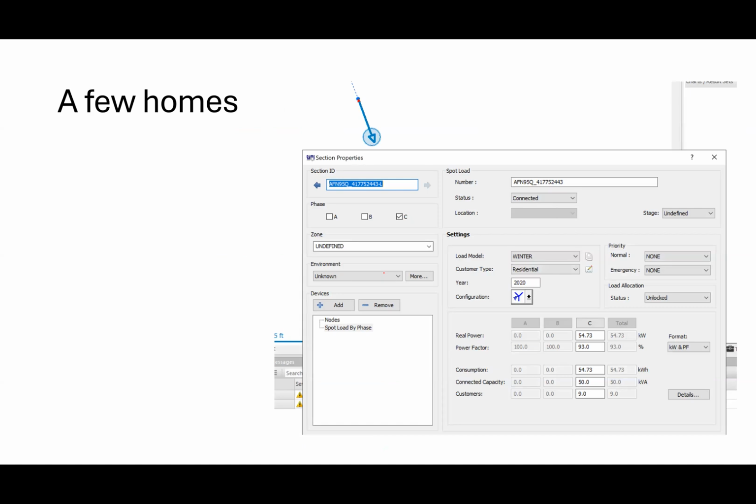And the example I gave here says, okay, well, here's a transformer. This is a diagram we use in one-line diagrams, which we'll talk about a little bit later. But basically what I see here is that apparently I have 9 customers, and it says my total load is 54 kW. So this is probably like a 60 or 75 kW transformer, something like that. Okay. That's not to say that's what the load always is. That's to say what the peak load is.